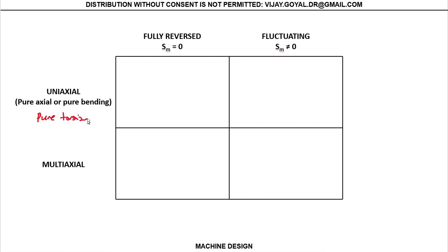Okay, if it's only one case scenario, one loading, then it typically is done for a fully reversed case, where your mean stress is zero, and this is what we call category 1. This is very popular. We got the test data for this, and it is well documented in many cases for many typical materials that we use, and we can use that.